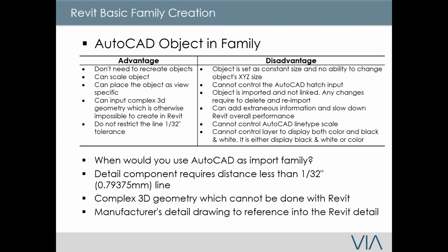All right. Now, sometimes when you have so many complicated families and you want to add them into Revit, AutoCAD objects are sometimes used. You can actually import them in. I know that some people say this is acceptable. Once your project gets so complicated, I would not recommend this method.